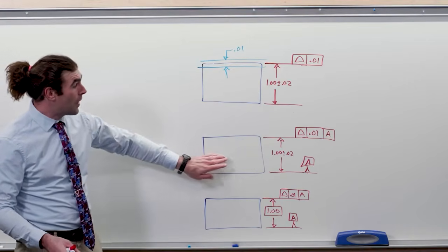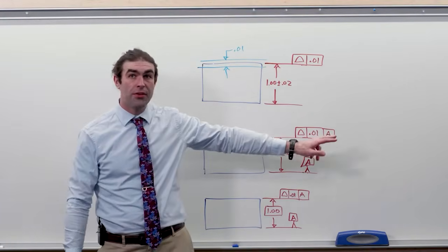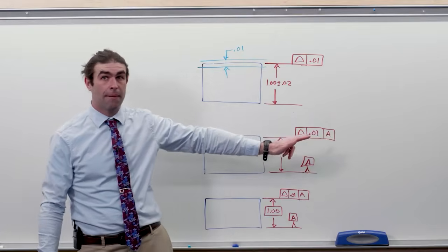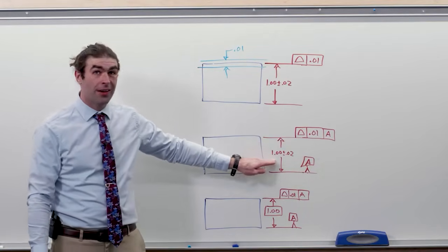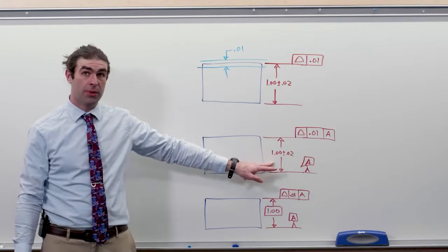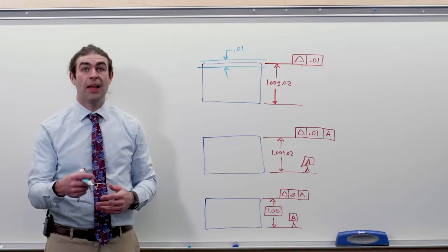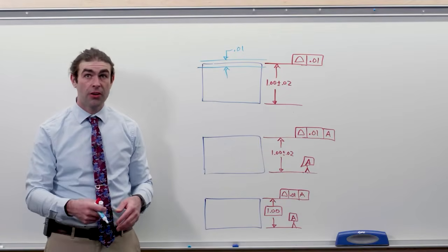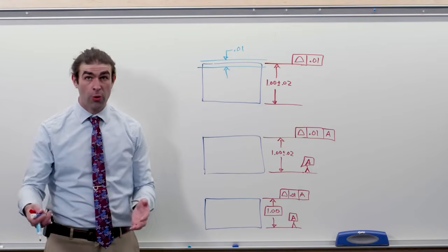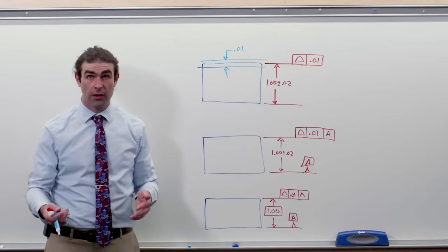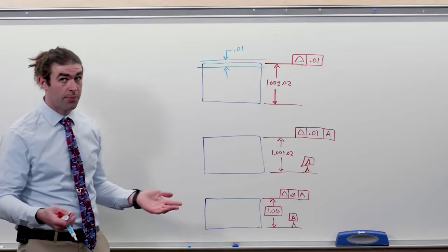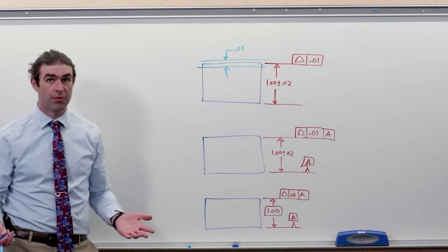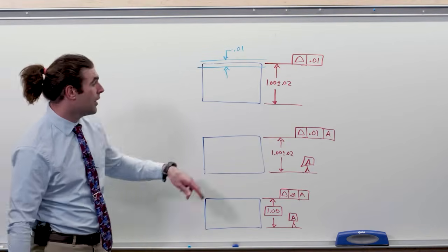The next one, we're going to use a profile of 10 thousandths to datum A. Now, what's important here is that we have a plus or minus dimension. Now, this isn't allowed per the current ASME standard. I'm putting it here just to show you how profile works. It's something you might run into. Not everybody makes every drawing per the current standard, right?